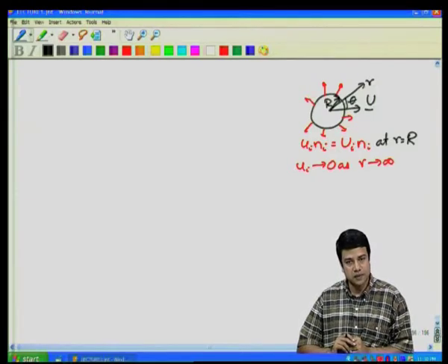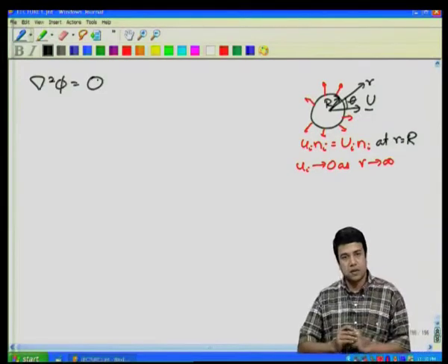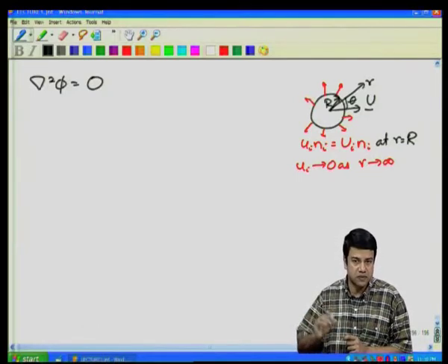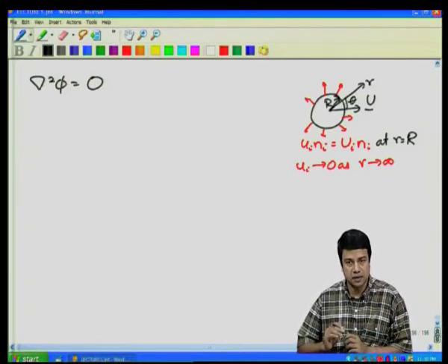We solved the potential flow equations in the last lecture. Del squared phi is equal to 0 with this boundary condition. Solutions are of two types, the growing and the decaying harmonics. Of course, we cannot have the growing harmonics because we require the velocity to go to 0 far away. Therefore, the solution has to be linear in the decaying harmonics. In addition, the velocity field is linear in the velocity of the sphere.